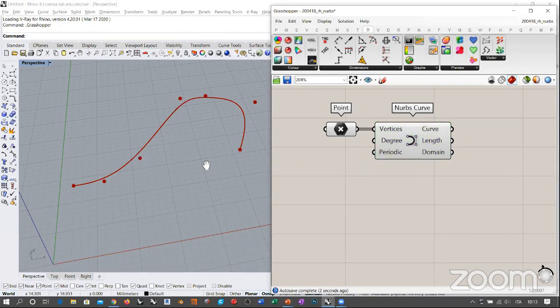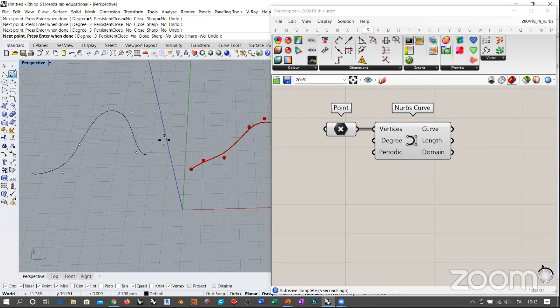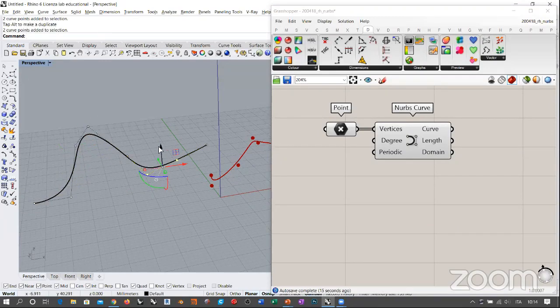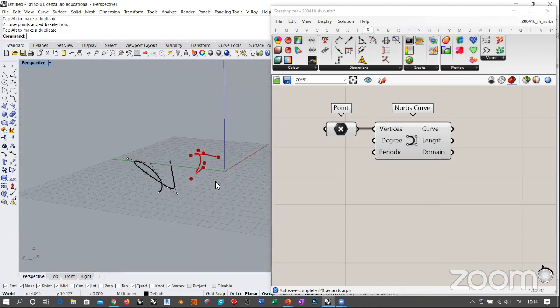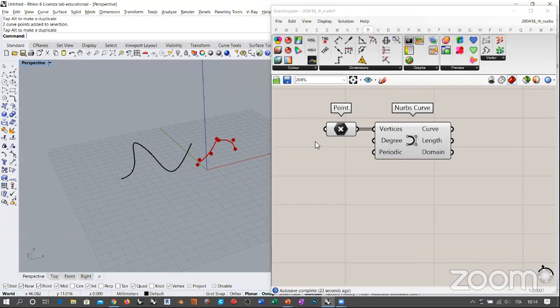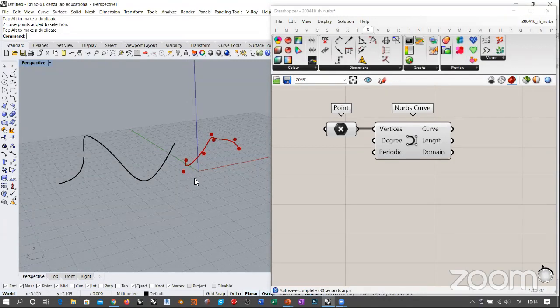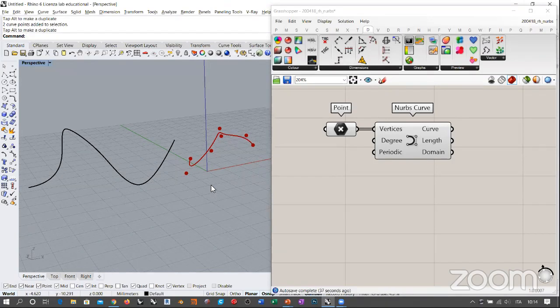And of course, I can create this curve in Rhino. I can simply click some points around and activate the control points, and then move some points up, move some points down, and get a very similar result to the original curve. Okay, so this is exactly what I'm doing here in Grasshopper. I don't know if you are all into Grasshopper, but in my opinion, if you don't have a perfect topological understanding of NURBS surfaces, you will encounter many troubles and problems in Rhino.